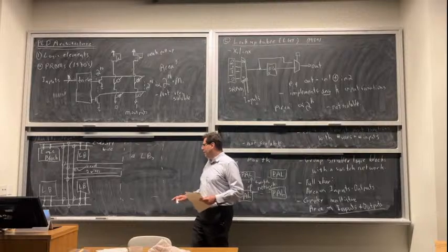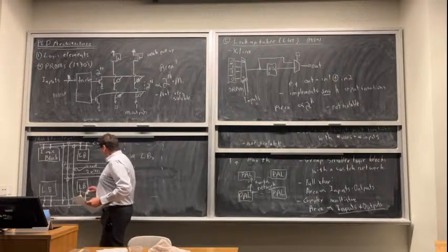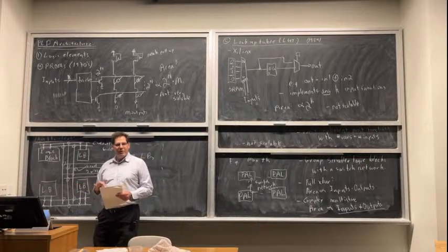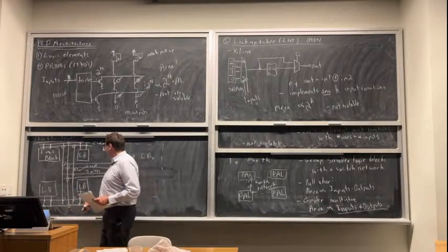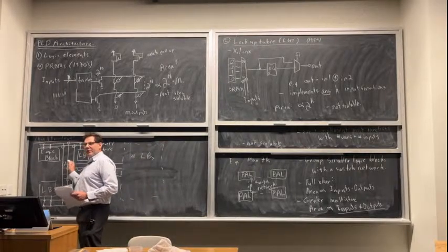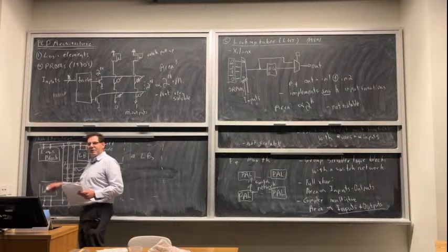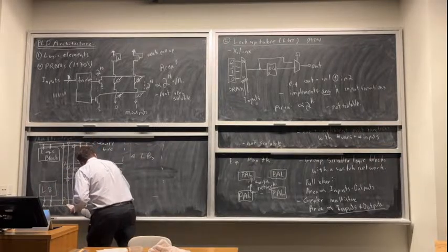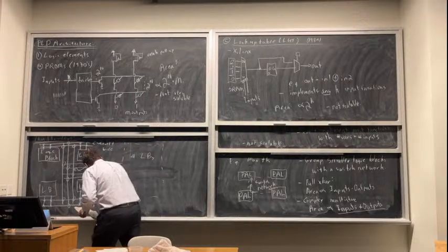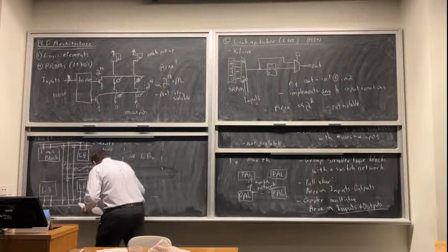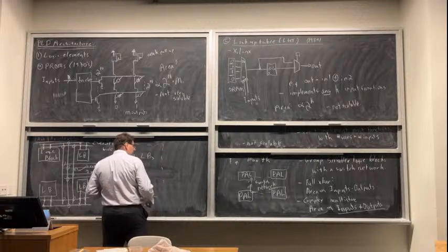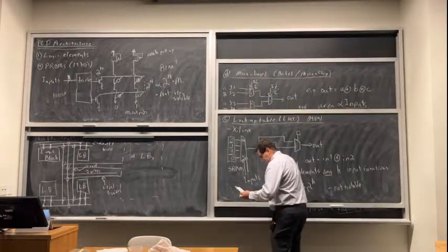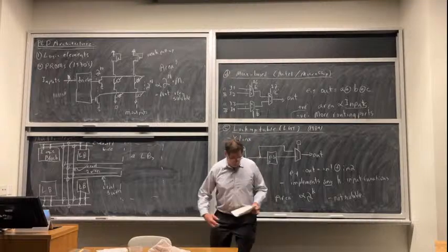So to have the area grow more slowly, I'm using sparse patterns of switches, and my CAD tools are going to have to figure out, can they connect it or not? And this will be one of the things I've got to figure out when I'm making the chip, of how sparse can I make these switches and it's still okay. So these ones now are the level 3 wires.